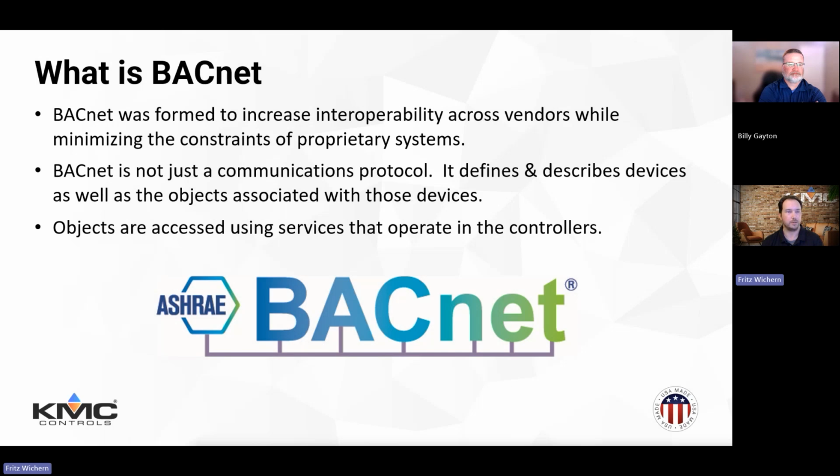And what's cool with BACnet is it's not just a communications protocol. A lot of times when we talk about BACnet, the first thing that comes to mind is just that communication protocol, but it also defines and describes the devices on the networks and the objects and services that those devices provide. There's a whole list of standards written out, and KMC prides itself on holding to those standards almost to a T, to where some of the things don't quite make sense to me, but they match the BACnet standard.